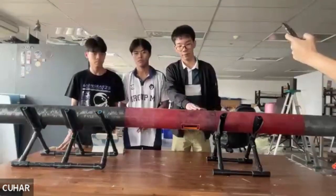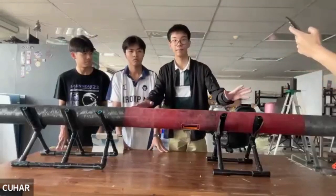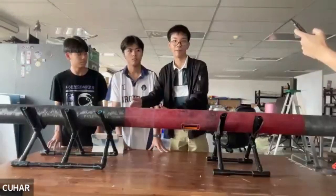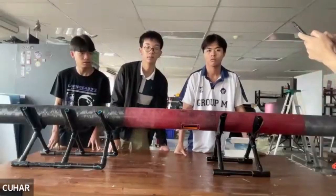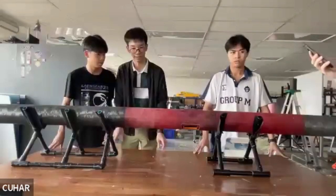Then behind the avionics bay, there will be the drogue chute section. So the main parachute and the drogue parachute each have their own compartment. This side is drogue. And just real quick, you're using nylon shear pins, I assume, for your separation points? Yes, held together until the charges fire. There will be a charge and a shear pin here, but not yet.